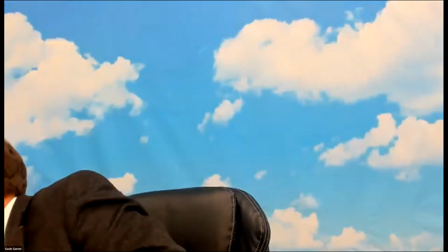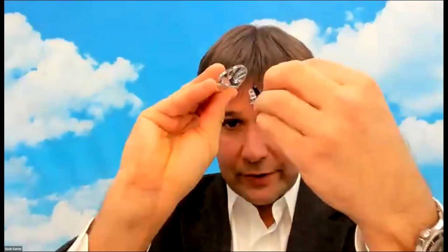These are on our systems with the motors. I've got acrylic discs that are very simple to laser cut to teach the students how encoders would work. I can demonstrate this later, but this is an example of a laser cut mirrored disc. And then this can measure where the spokes are as this rotates over it. And again, I'll show you that in action in a minute.